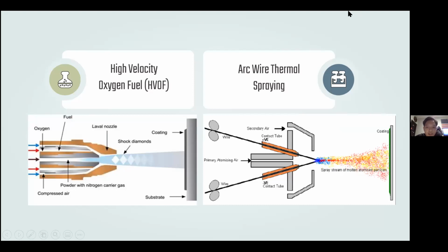And these are the last two of the techniques. The first one is high velocity oxygen fuel, or HVOF. HVOF is a thermal spray system that uses the combustion of gases like hydrogen or liquid fuels like kerosene to produce heat. Within the combustion area, fuel and oxygen combine and atomize under conditions that ensure the proper combustion mode and pressure are maintained. The method generates a high velocity jet that is employed to drive the particles at near supersonic speeds before impacting on the substrates.